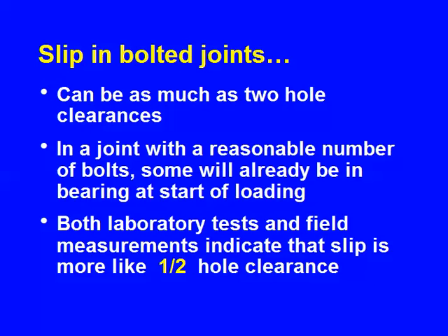My premise is that we should not be specifying slip critical connections unless we need to. You have to know when you need it, like fatigue. That's the most obvious example. I'll give you some more help as time goes on. But don't do it just because it's the more conservative of the 2 choices. We're competing with other people and other industries out there, and we don't want to make our steel structures more expensive than they need to be. So if you don't need slip critical connections, don't specify them. And for buildings, almost all buildings don't have to have slip critical connections.